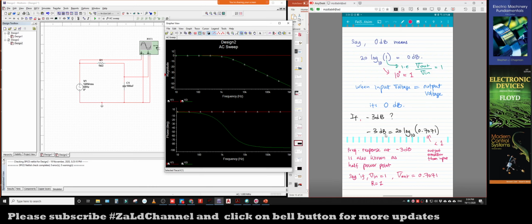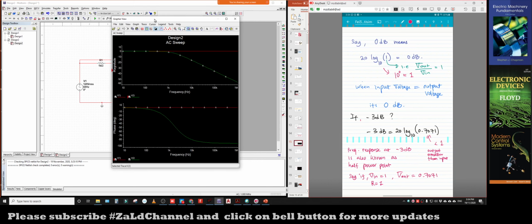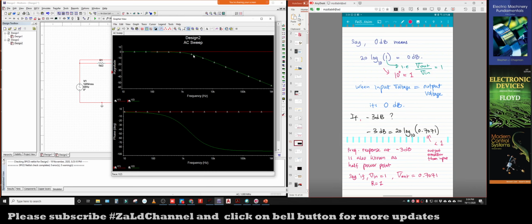So -3 decibel signal. When we take the negative decibel, for Multisim we cannot do specific coordinate tracing here. Unlike LTspice, where we can do it, but for Multisim we cannot. So just assume that -3 decibel is around here. So when we plot the output, it will be at some point more than 1000 hertz. All right, that reflects -3 decibel.